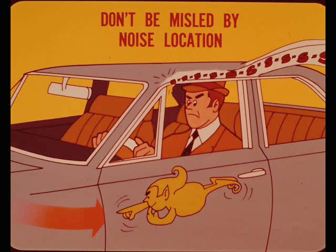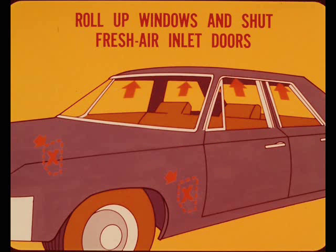And be sure to remember, small holes can make large noises. Thank you, Tech. Now, when you're satisfied with the general condition of the weather strip and door or body surfaces in the noise area, roll up all the windows and shut the fresh air inlet doors so you can close off the interior to run a body air leak test.